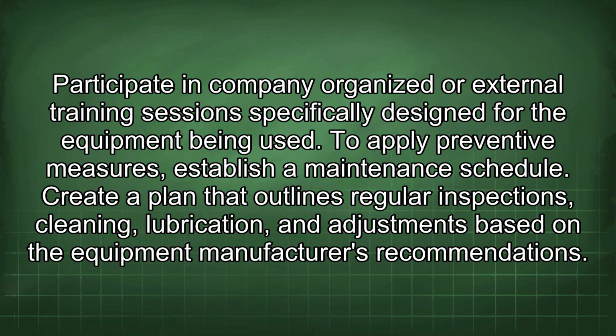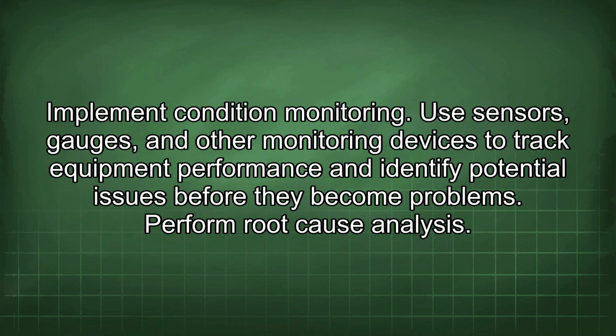To apply preventive measures, establish a maintenance schedule. Create a plan that outlines regular inspections, cleaning, lubrication, and adjustments based on the equipment manufacturer's recommendations. Implement condition monitoring. Use sensors, gauges, and other monitoring devices to track equipment performance and identify potential issues before they become problems.